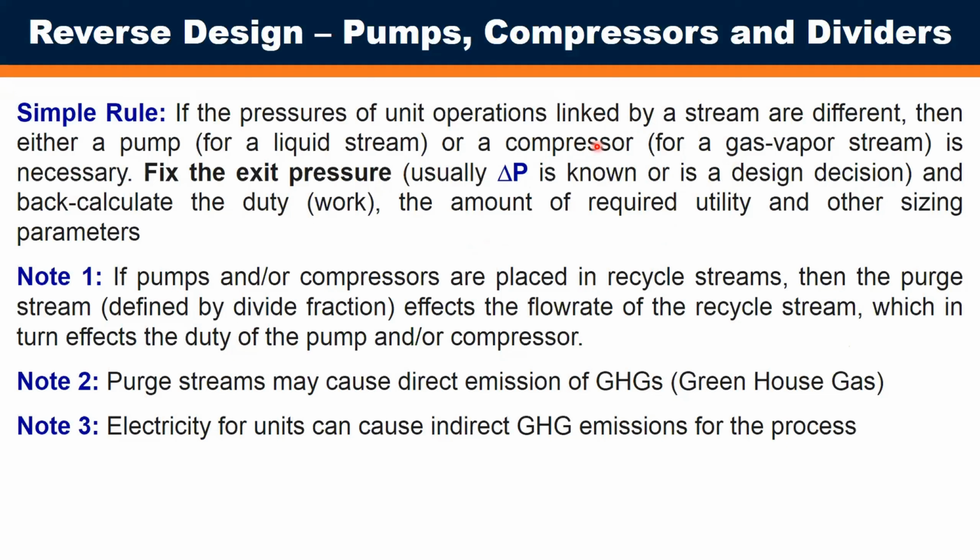That depends on the specific conditions, but it's not always that you do everything on a gas stream with a compressor. It depends on the PV work, whether or not the compressor is the best way to change the pressure, or if you condense it first, pump it to the higher pressure, and then re-vaporize it. But that's a side note.